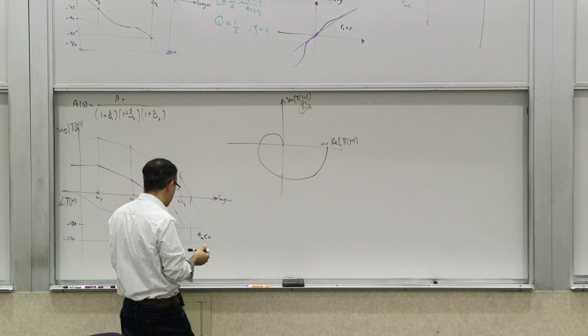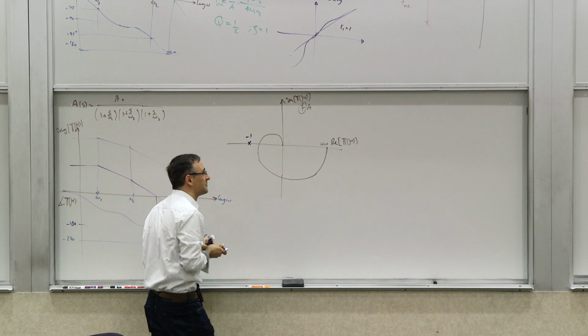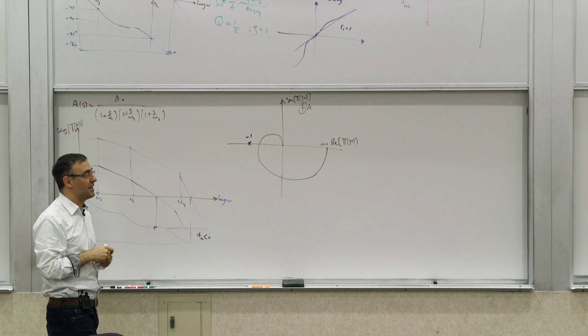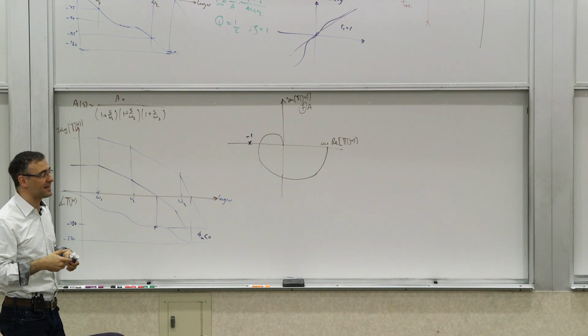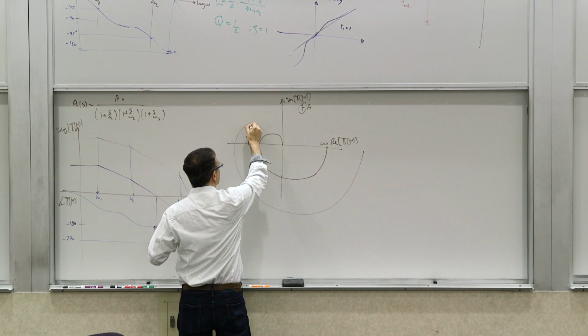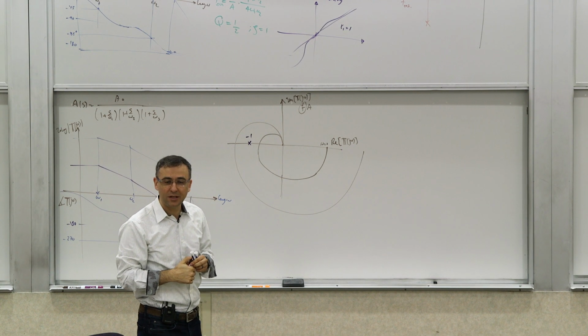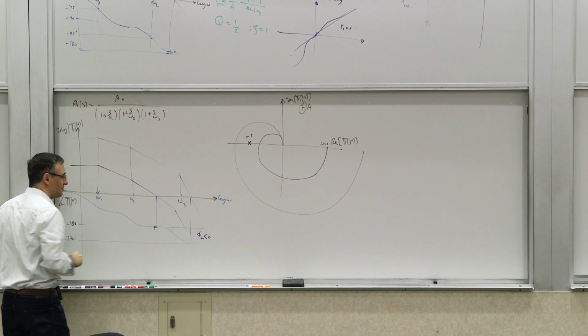So depending on where your point negative 1 is, if I say point negative 1 is here, it's stable for that f. As I increase f, this is going to become a different plot, and it can encircle it, which you can also see in this picture.